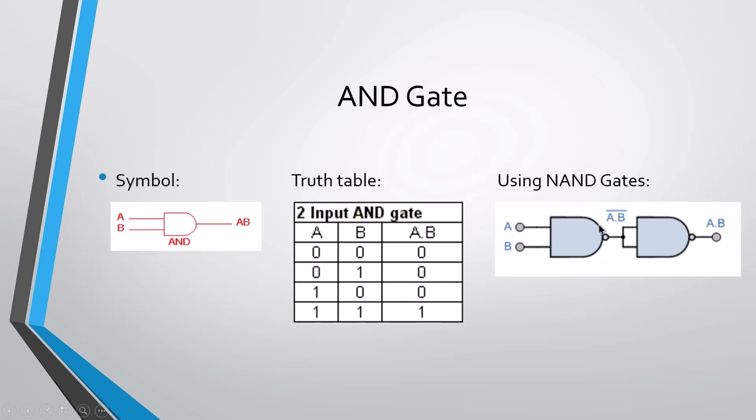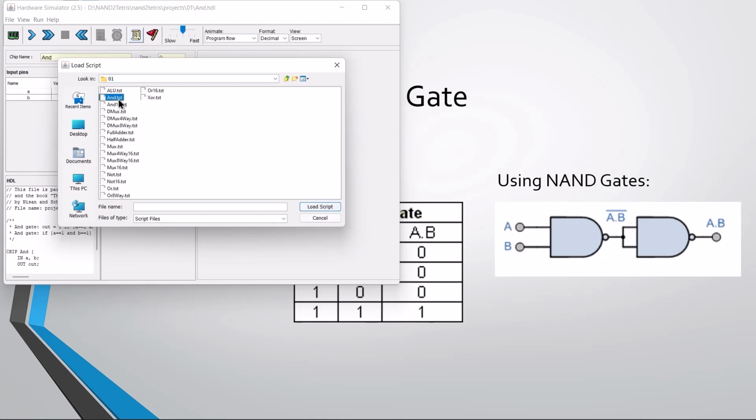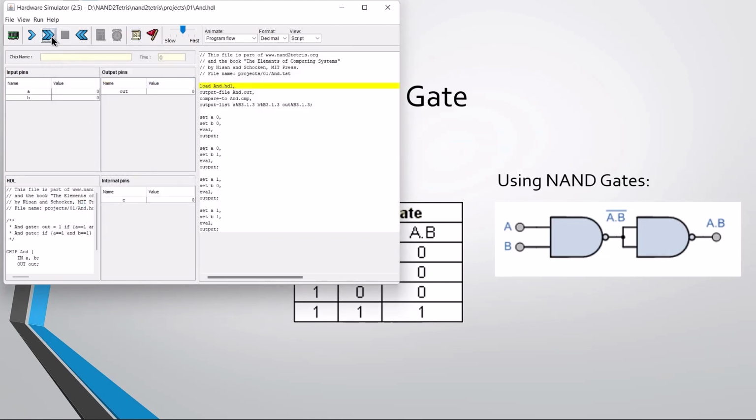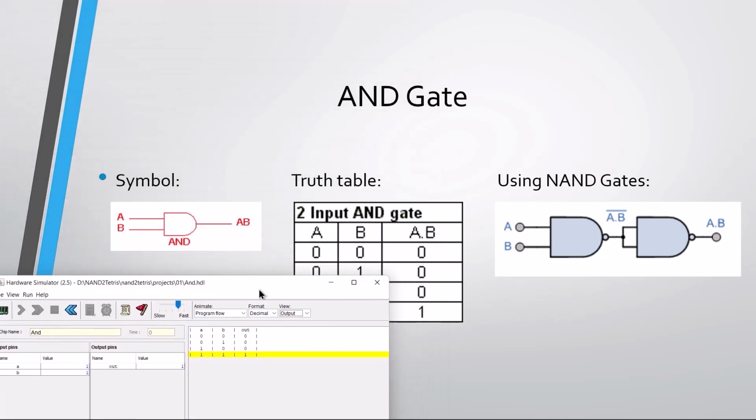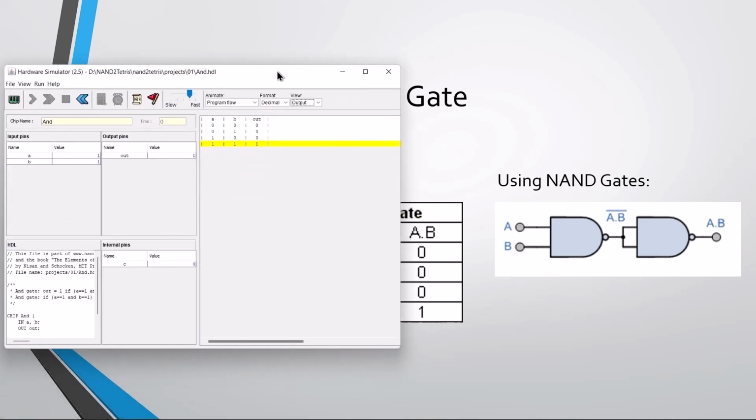Now I will implement it in the hardware simulator in the NAND2Tetris course. And if we compare the outputs here, 0001 and 0001, they match.